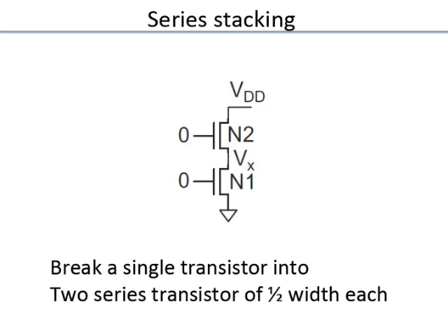So if you want a truly portable design, this might be better, where all transistors are minimum length. Then you take the design, put it in another process, and you can still expect two series transistors to be slower than a single transistor. Whereas a transistor with twice the length, because of the reverse short channel and short channel effect, depending on the process, you might not get what you want.